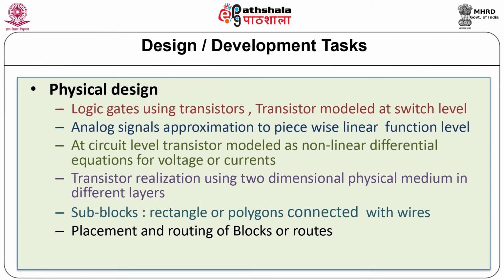Physical design. Logic gates are constructed using transistors. Designing at transistor level demands a different level of dependence on the requirements. Transistors can be modeled at the switch level as bidirectional switches. At the timing level, signals are considered with a piecewise linear function. At circuit level, transistors are modeled using nonlinear differential equations for currents and voltages.